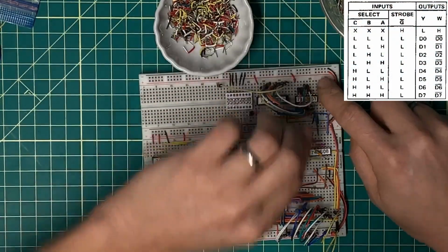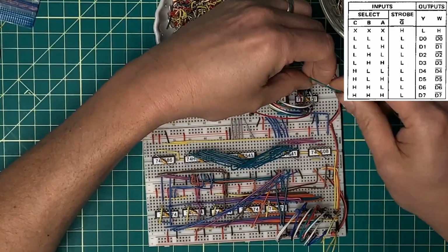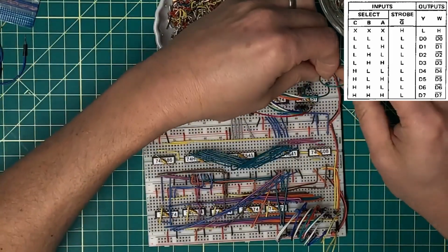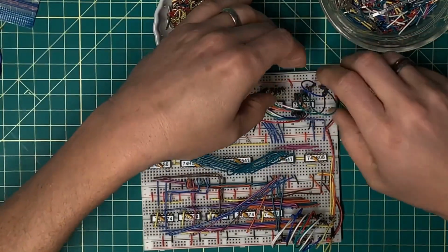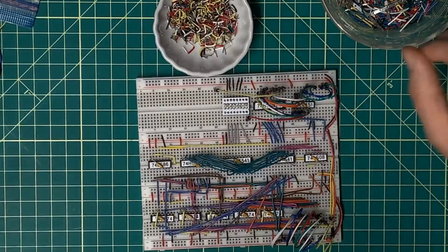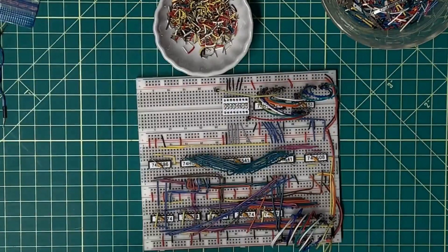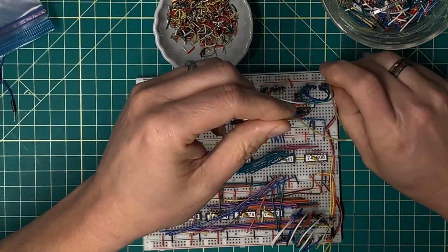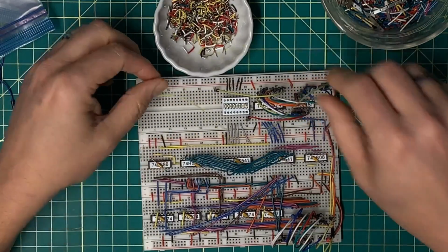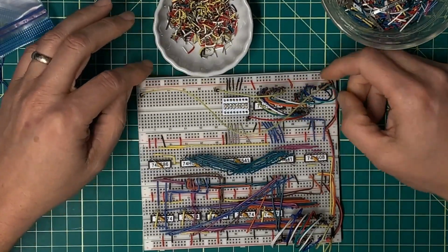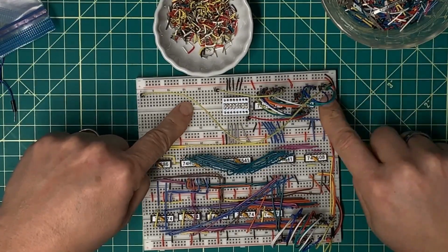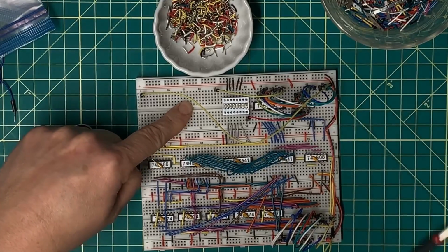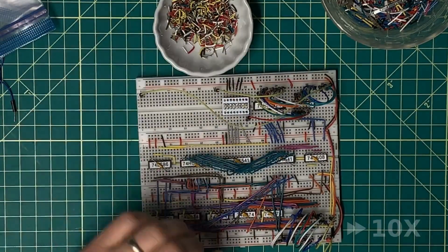And then I've got A, B, C, A being the least significant bit, B being the next one up, and C being the most significant bit. That's going to be the most significant bit of my 4 bits to select which one. And then my genuinely least significant bit is going to be landed over here someplace. I will need to take that to the XOR gate over here somewhere. But this now gives me a place to land my control signals in. Let me clean up this wiring a little bit.